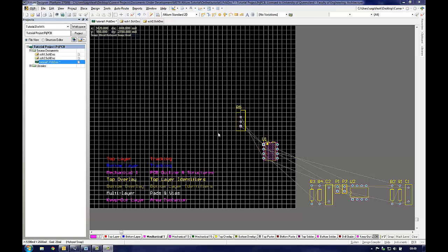When a circuit has to fit inside an enclosure, it is common for the enclosure designer to dictate the space constraints of the system to the PCB designer. The enclosure designer will usually specify the size of the circuit board and how it will be mounted within the enclosure. This can often be a difficult constraint for the circuit designer to work within, and it is important to establish whether or not the circuit design is possible within this constraint at the earliest stage.